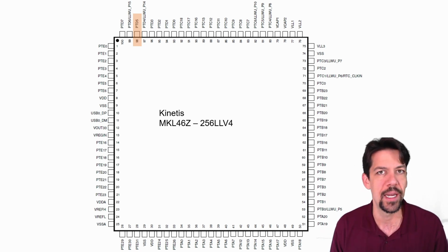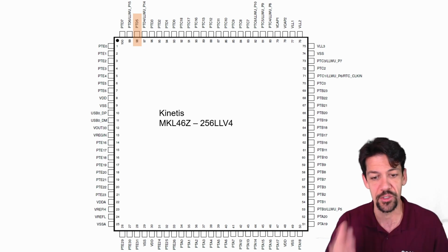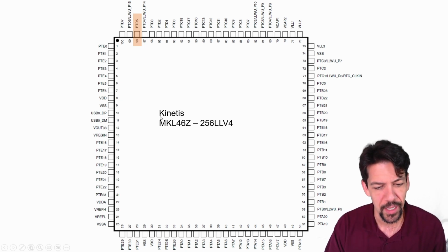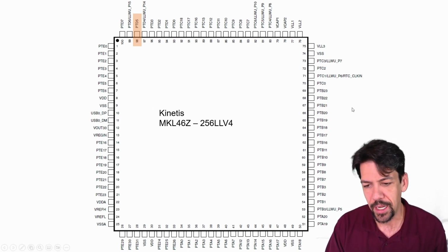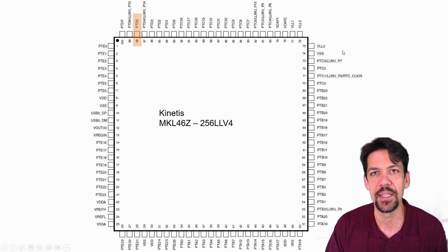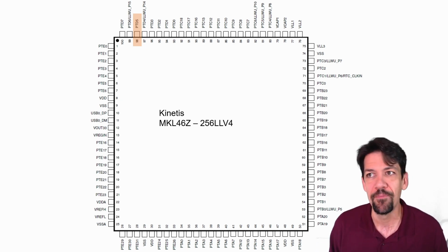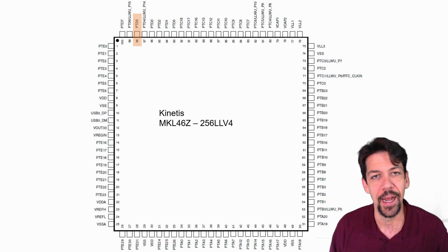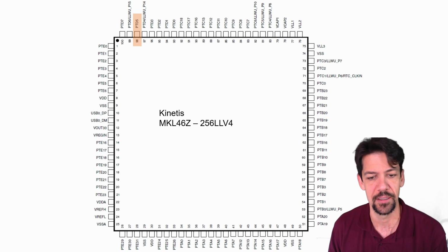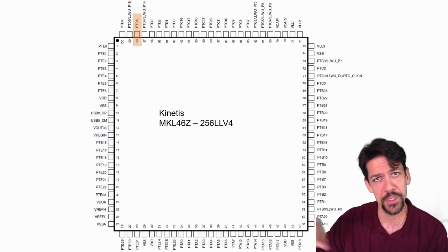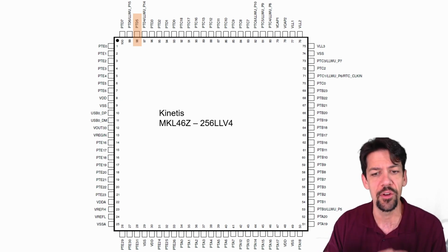There's only so many interfaces to the outside world. There's only 100 pins. Maybe 10% of them are taken up with voltage and ground pins, communication interfaces, things like that that support the electrical functionality of the chip, and maybe 80 pins are left for general purpose I/O and communicating with the outside world and doing things, right? So the processor is very, very capable, and to be flexible for multiple different applications, it's set up so that you can configure each of these pins to do different things.